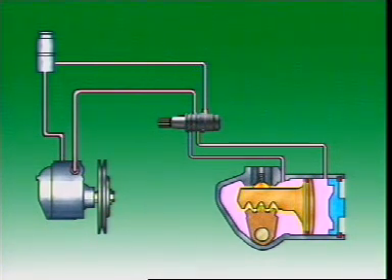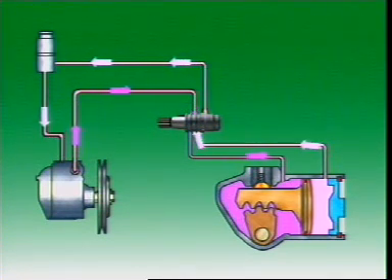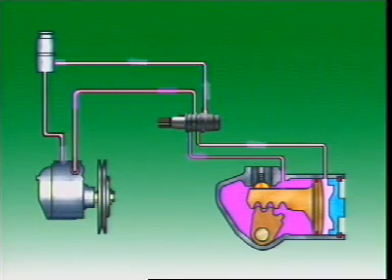It has an extension formed on one side, with teeth which engage teeth on the pitman shaft. Pressure applied to either side of the piston produces a force, which is transferred through the teeth to help turn the pitman shaft.